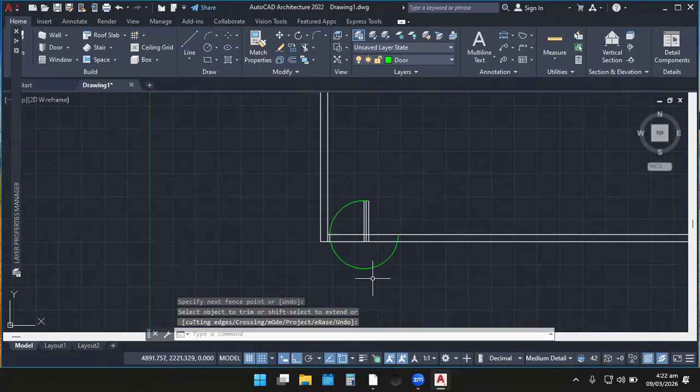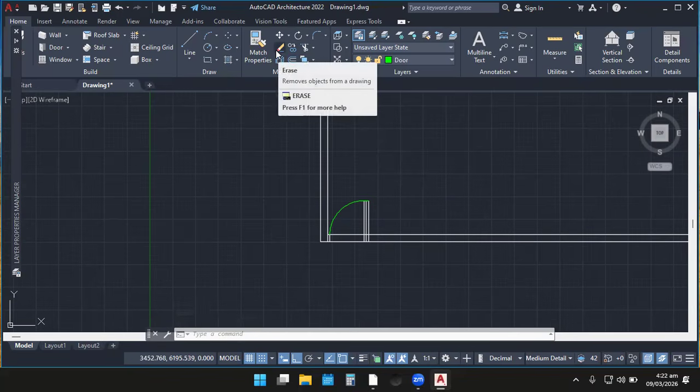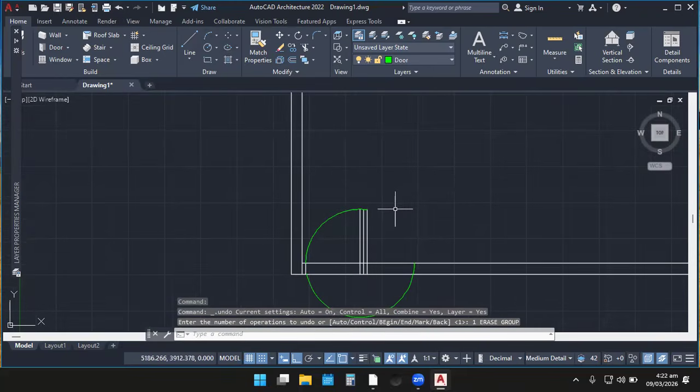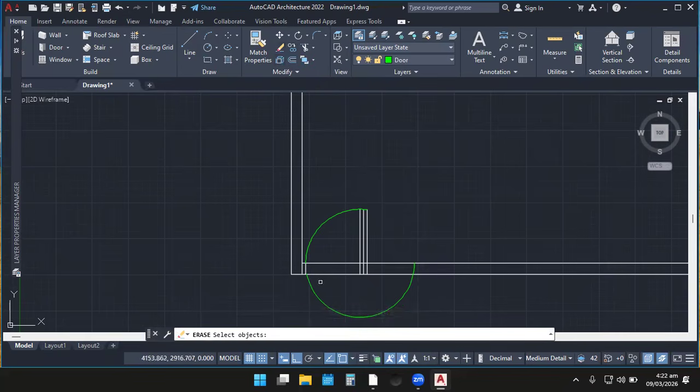I can just come and select this line like this. If I select this line, then I click delete on the screen. You see that it is gone. This is the delete, or let me say erase. After selecting erase, it was gone. Let me quickly undo and do that for you again. What did I do? I click on erase and see a pencil with an eraser. Then I just come and highlight that part or just click it. When I select the object, I press enter on the keyboard. It is gone. Okay.